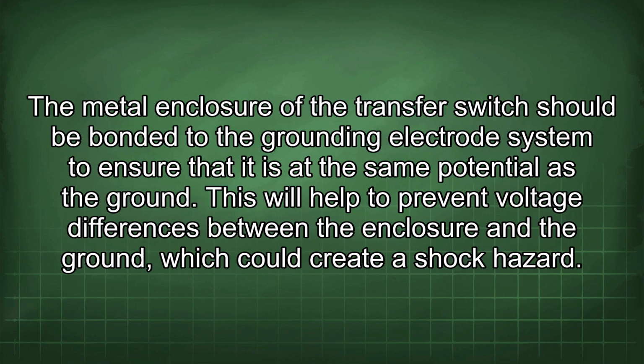The metal enclosure of the transfer switch should be bonded to the grounding electrode system to ensure that it is at the same potential as the ground. This will help to prevent voltage differences between the enclosure and the ground, which could create a shock hazard.